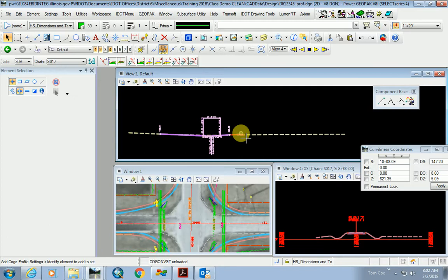And normally on projects, you're going to have a curve. And so you're going to use the same tools, though, regardless of if you have a curve or not. If you do have a curve, I'll show you that Geopak will calculate your super elevation for you, your transitions, all that sort of thing. Or even if you're trying to match existing, you're going to find out from Geopak if the existing meets policy based on your design speed.